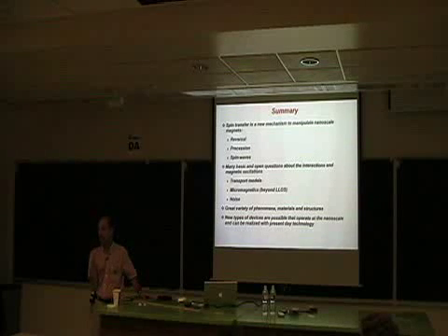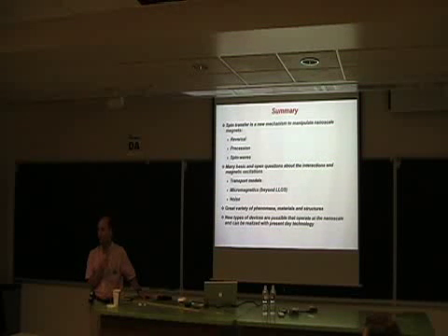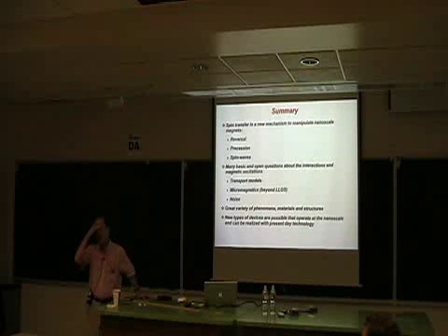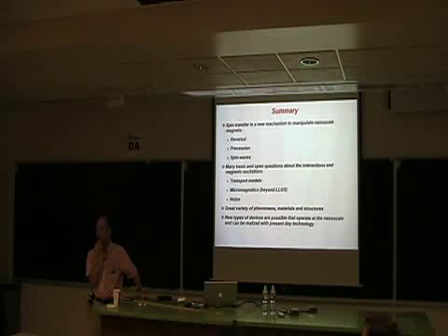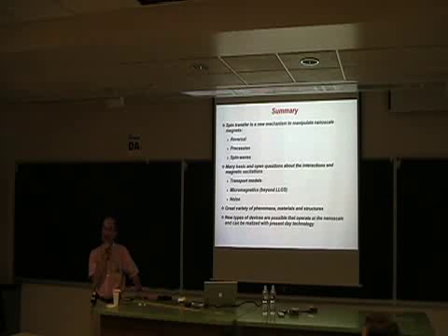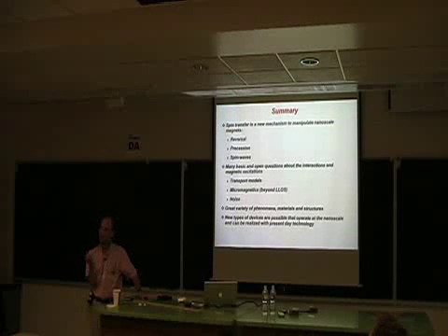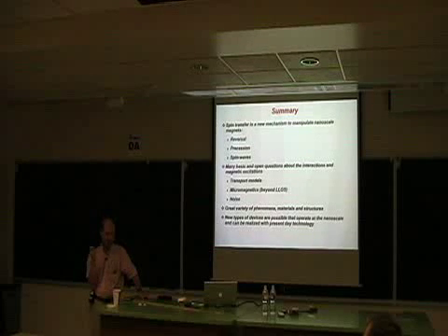There's a great interest in actually replacing that metal with a tunnel junction, and the reason is the resistance change is much larger with magnetic tunnel junctions. Would there be Coulomb blockade? At the scale of 100 nanometers, you're beyond the Coulomb blockade. Maybe at very low temperature you would have Coulomb blockade, but the interest is in applications. Tunnel junctions provide a much larger signal.